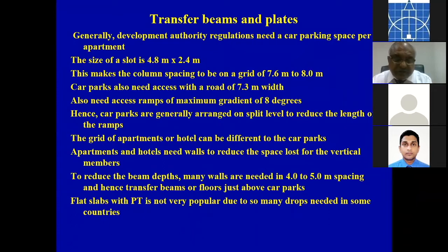So increasing the area to improve the flexural capacity is not very efficient. But because we have a restriction on the height of the beam to about 600 millimeters, to ensure that plastic hinges will always occur within the beam, not in the column, it's worth having a wide beam.